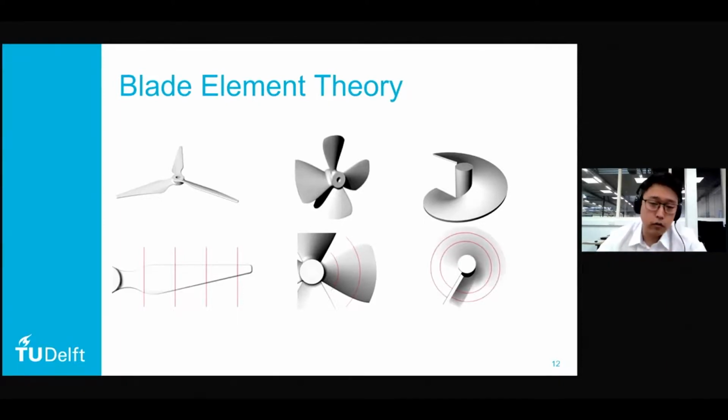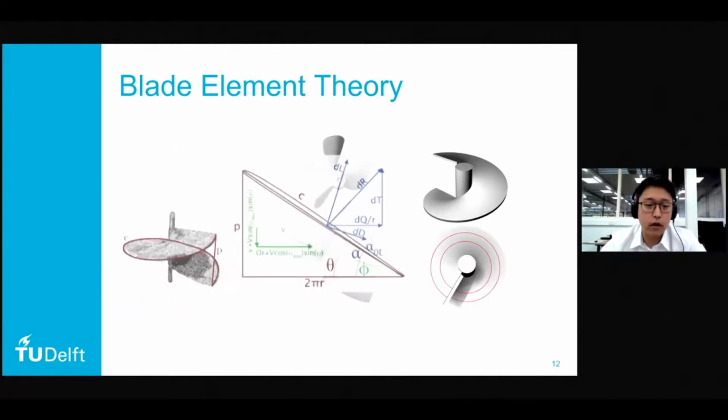Of course, since our aerial screw sweeps a full revolution from the leading to the trailing edge, we end up with essentially circular slices. And we unwrap these into a flat 2-dimensional case, and we just end up with a very long chord. And then we just do lift calculations, we do drag calculations, and we integrate along the rotor blade from the root to the tip to get the total thrust and drag and the power, sorry.